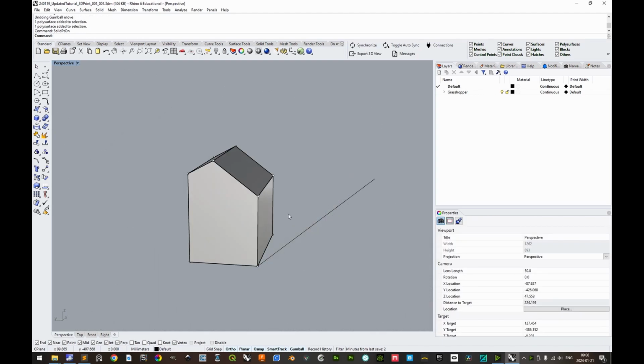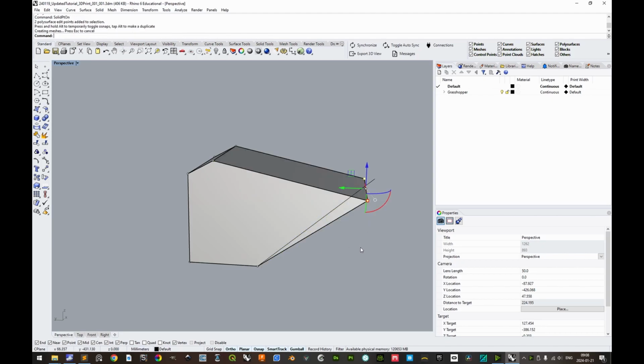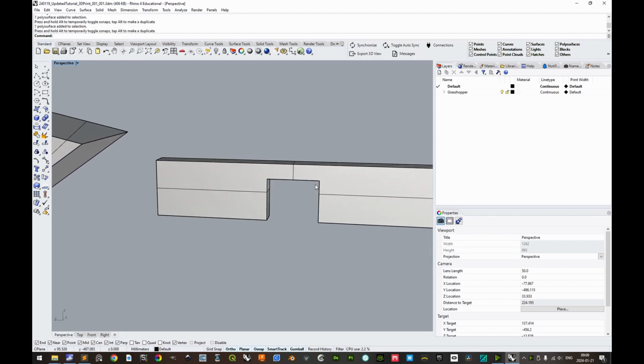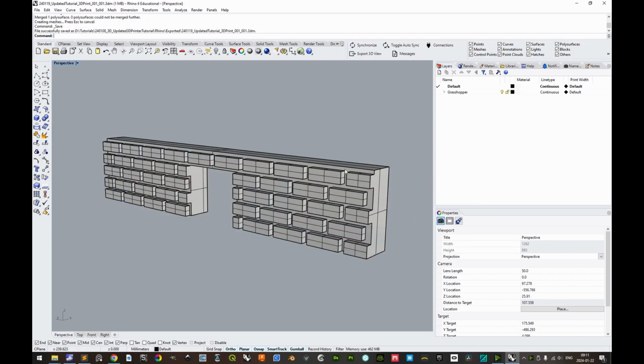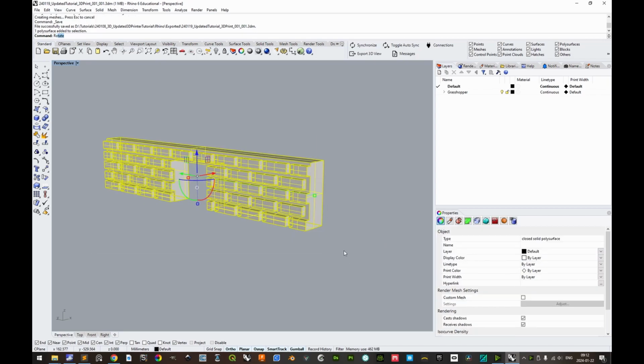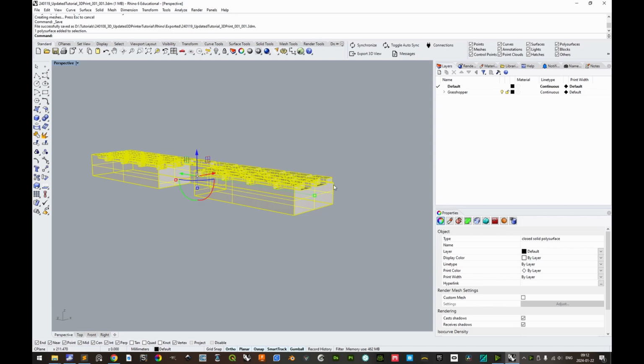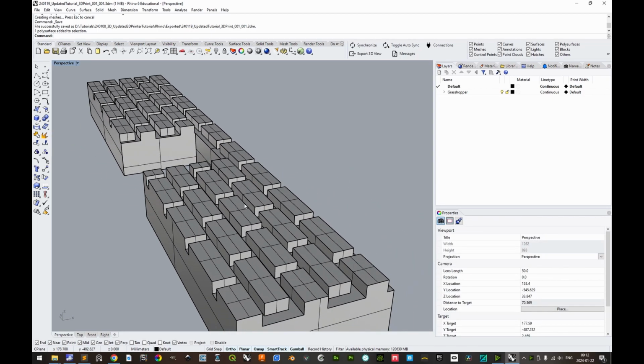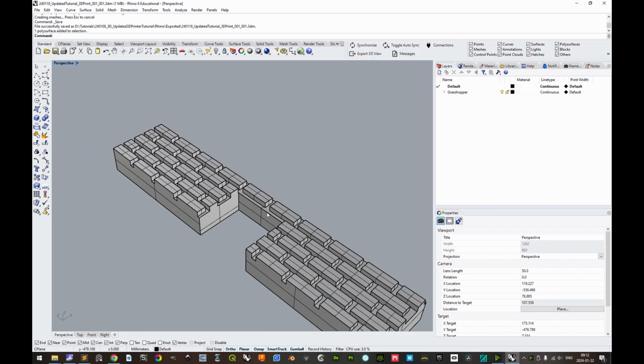Overhangs extending more than 50 degrees will need support geometry generated below to reduce the risk of sagging due to gravity. Cantilever geometry and horizontal elements above void will for the same reason need support geometry as well. If you have a model with many of these overhang sort of like pseudo cantilever geometries, which would create a lot of support geometry underneath that would have to be manually removed, it may be wise to simply rotate this so that you have a flat bottom and no need for support when fabricating this element.